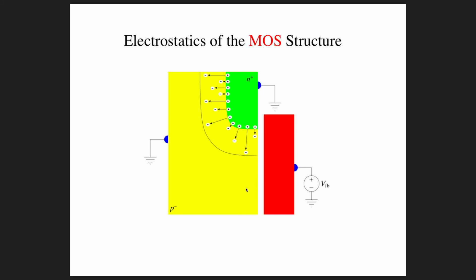And so we start out P-type, but then because we're putting these gate charges on and sending the holes away, we create this depletion region. And by the time we get to above threshold, our mobile charges here at the surface have inverted their type, right? So instead of being holes, they're electrons.